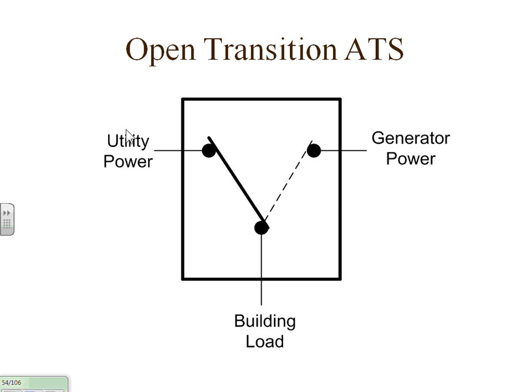The third time delay that's in all transfer switches is a time delay on retransfer. I'll give you a situation for that too. Hot day, summertime here, extremely warm. Everybody has gone over at some point and turned on their air conditioner, or they've got it set on the thermostat. All the air conditioners are running. Utility fails. Nobody that I have ever talked to has told me, boy, as soon as the power failed, I ran over and turned off my air conditioner. Never happened.